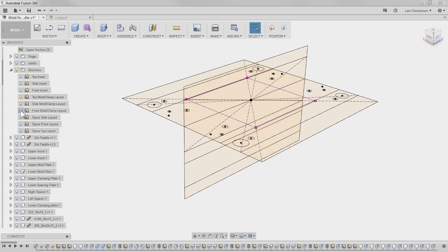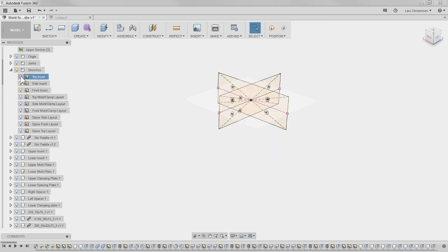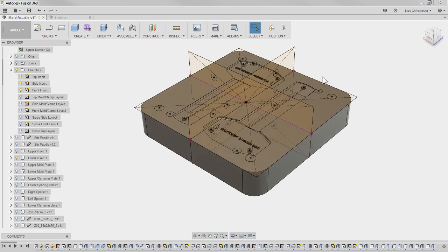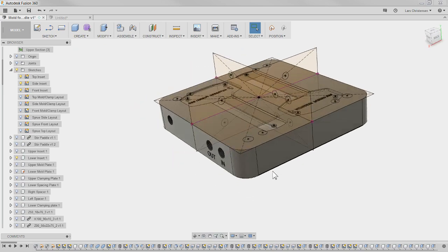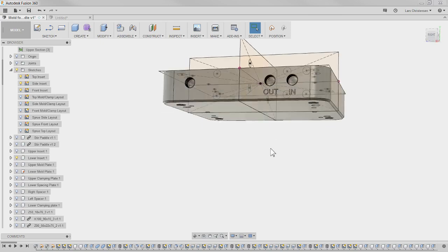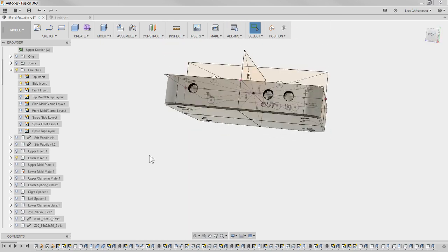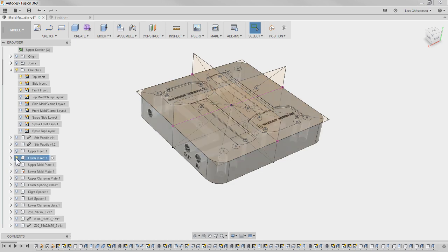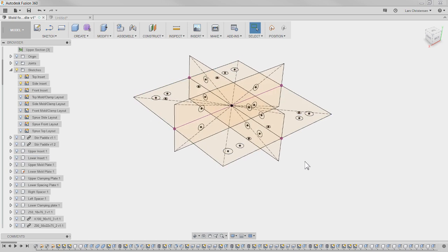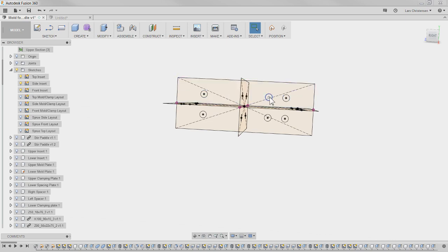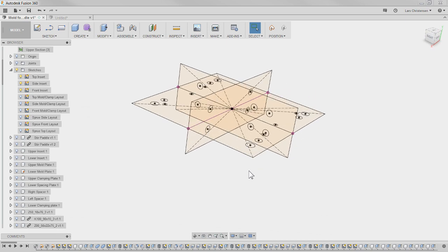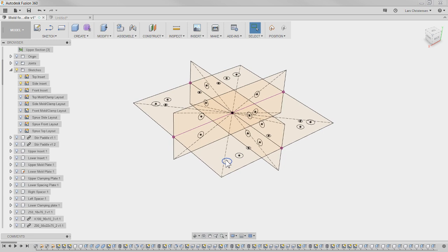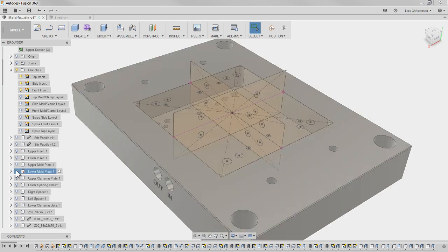One of the most obvious things probably is if you're looking at the insert, the upper and lower insert for the mold. In here, there are a couple of different things. There are water channels running in, some screw holes and some dowel holes, and it's all controlled through sketches. The coolant lines are controlled through these sketches, and the dowels and things are controlled through these sketches.